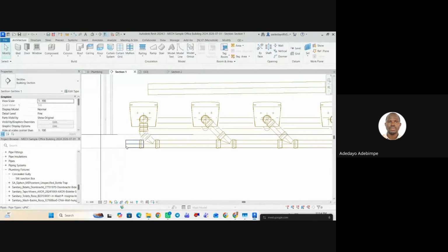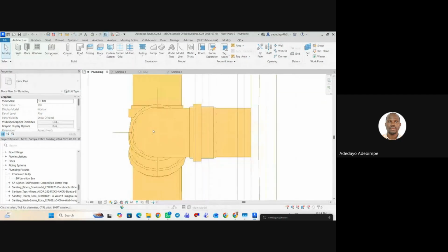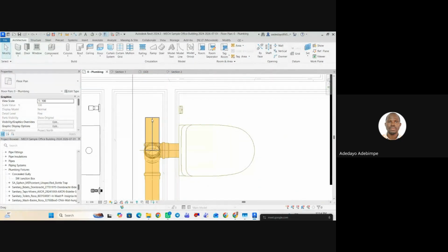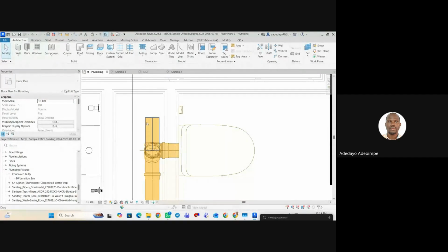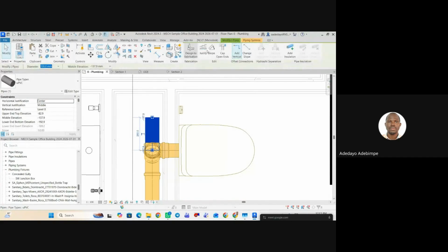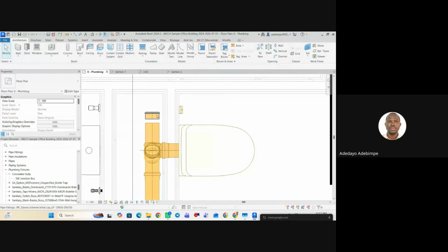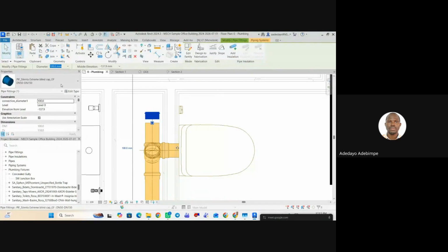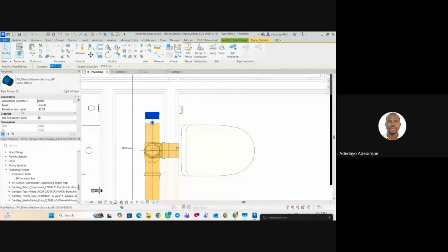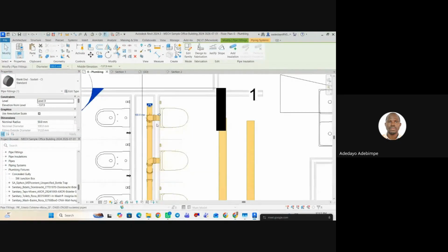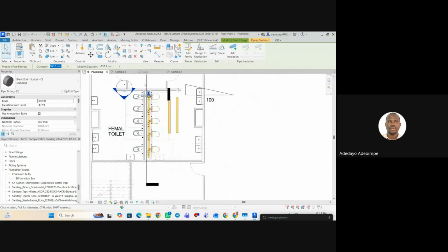And let's say plumbing. So maybe it is going to open to the toilet somewhere, or let's just leave it inside the shaft and right click on it. Let me just cap open end. So I want to add a cap to it to show that they have to cap it, maybe it's a clean out of some sort. So I can change the type of fitting. I prefer something flat. Yeah. So I'm using that to indicate my clean out now.